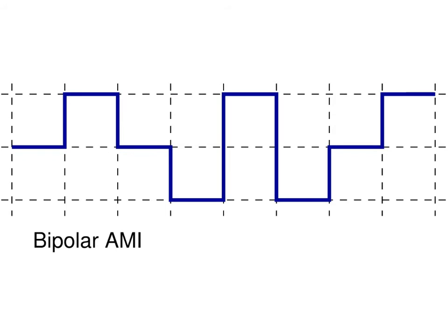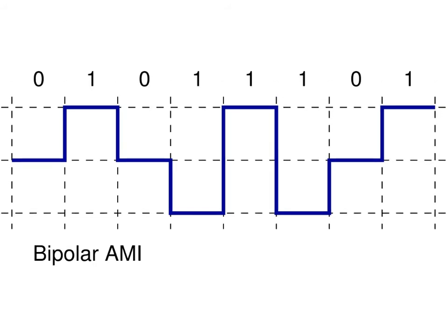First bit 0, this is 0 volts at this level, so 0, 1, back to the 0 line, no line signal or 0 volts, so it means a bit 0 here. So here's the alternate, positive, negative. And we see positive, negative for bit 1s, positive, negative, positive, negative, and keep going like that.